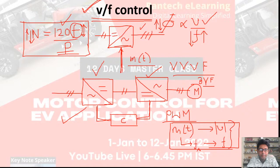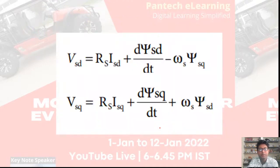For the closed loop, you should take the RPM and the current feedback, and you can use some PI regulator or PID, and based on that your modulation index and the modulating signal frequency can be altered accordingly. So this is the very basic fundamental concept of V by F control. Okay. Now today we will be knowing the governing equations which will be required for vector control.